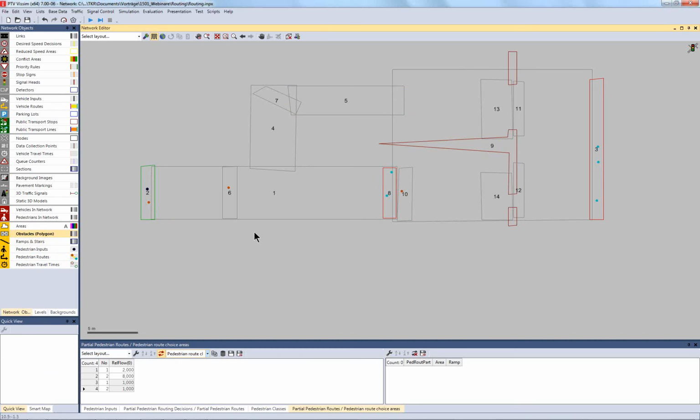So now pedestrians have to decide already here, where they might not see what's going on in front of the second bottleneck here, if they walk the straight line or if they pass or go the other way through the former dead end. And to do so, I just take away the former dead end partial route and I change the position of the density-based partial route to this area.